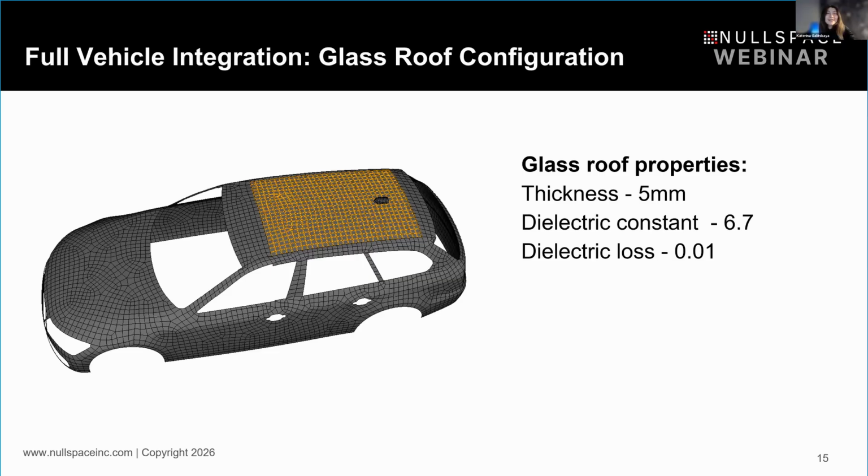And they most likely want to use the same antenna. I would suspect that they want to use the same shark fin antenna or something, and inside it's the same, all the connectivity systems that you have inside are the same, but the environment has changed, right? So it was very interesting for me. You need to think about that. You need to design your antenna to work in several environments simultaneously. That's of course possible, but that is a challenge and that's something that you need to consider when you design this antenna.